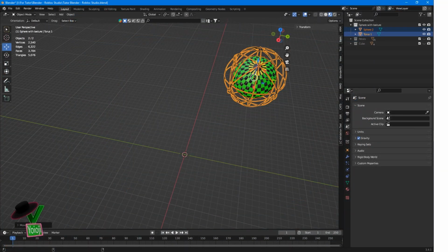center of the stand. That is, if in Blender the model, the parts of which it consists, were located at a certain height and distance along the coordinate axis from the intersection point of all coordinate axes, then during import all this will also be preserved. The model axis will be the center of the model object itself.